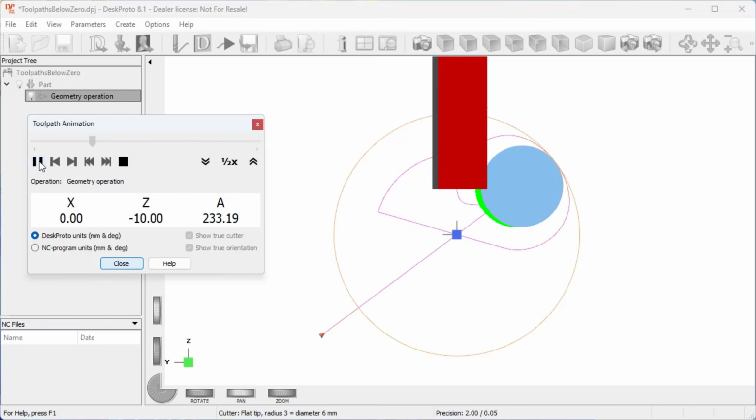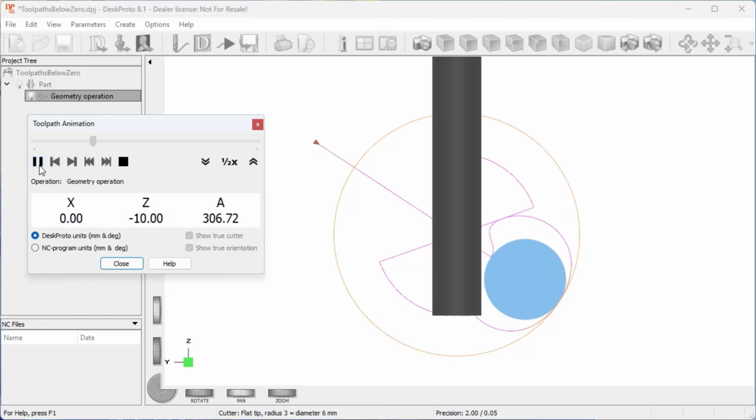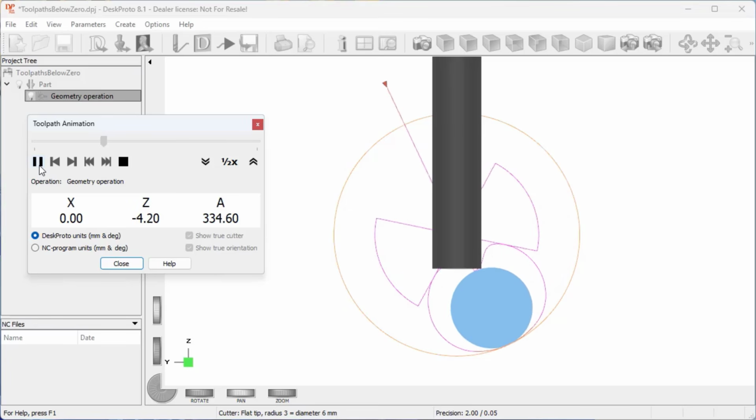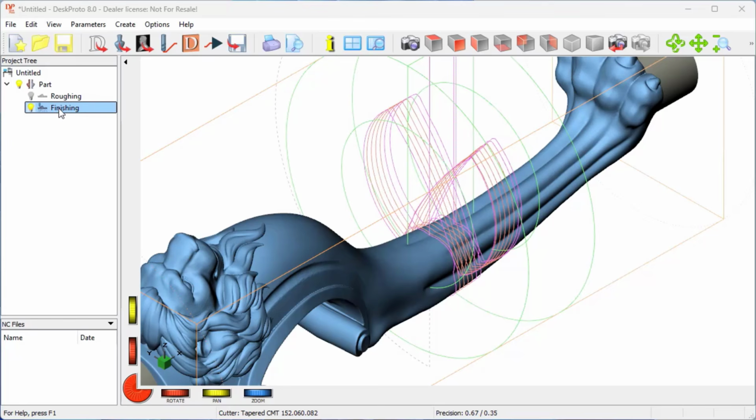Now the part will be a bit too thin instead of too thick. So as a result, a ridge will be present on the surface, which is clearly visible in the resulting part. So far the explanation of the butterfly wings and why the 0 point for rotary machining needs to be very accurate. Now I can finish the project.